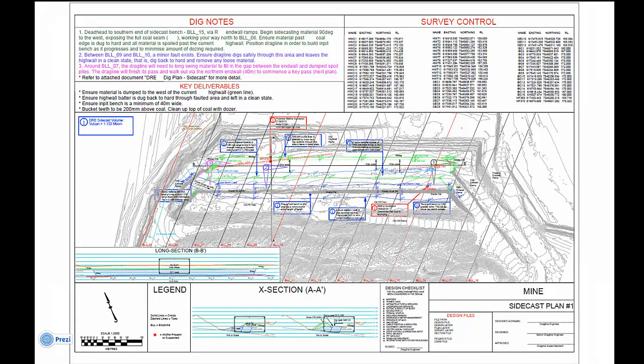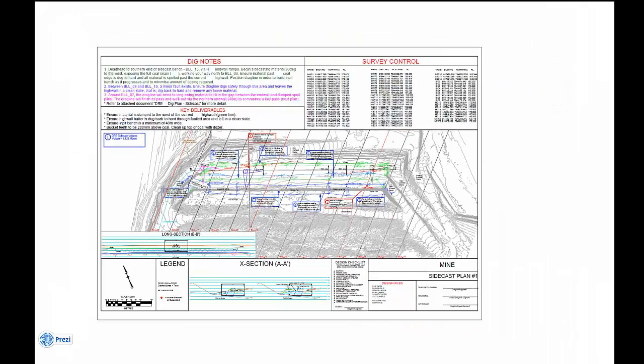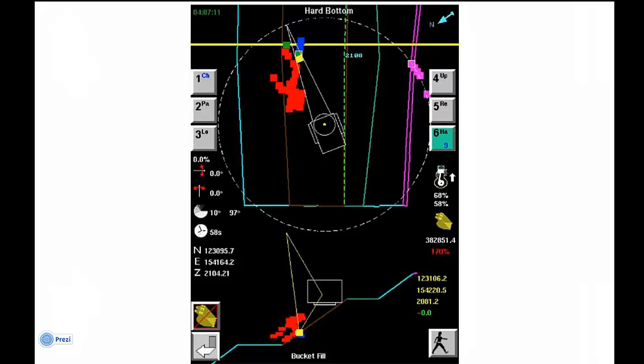When all the design work is completed and ready for implementation, it needs to be communicated to the production personnel, so generally the superintendents and the operators. The usual way is through visualizations like plans and presentations. Another common practice is through real-time GPS monitoring software. There are packages like Aquila and Pegasus, where the engineer uploads the design files directly to the dragline and the operators are able to dig exactly to the design lines.